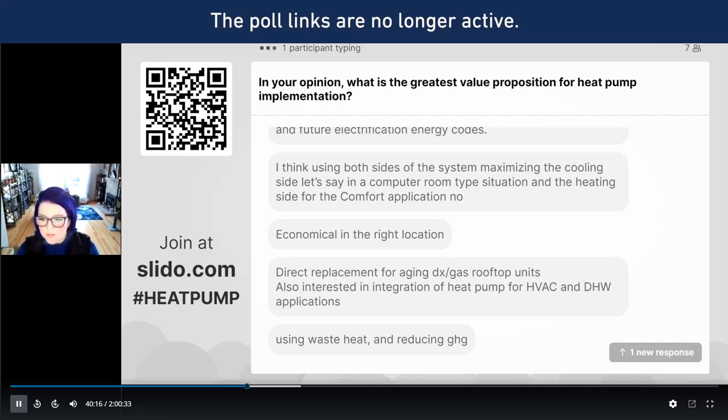So clients who did get heat pump systems would often have to add an auxiliary electric or gas pack accessory in order to have that emergency heat when needed. So they have come a long way just due to refrigerants and its advancements in the last few years. They're able to stay in operation below zero. So that is fascinating to me.